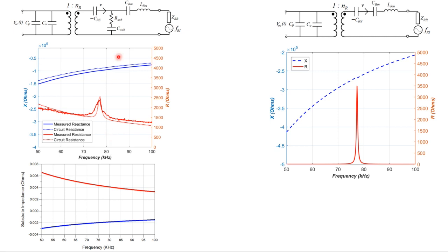The RC branch has both real and imaginary parts, and the reactive part of the substrate leakage can be thought of as a compliance of the backing plate. So you can think of it as a bilateral CMUT. For very thin substrates, we know that the peak displacements are not zero, as in the case of rigid substrates. So there is a certain displacement.